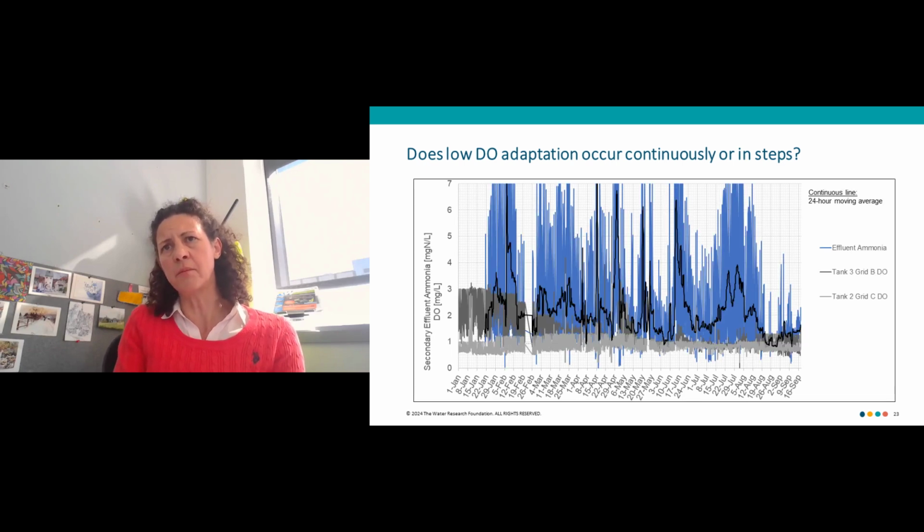And I overlaid here for the same time period the effluent ammonia concentrations, because there is a variability diurnally. You see that this data looks kind of smeared, but that's just the diurnal variability of ammonia in the effluent. And specifically, I don't have a pointer, but look at August of this year. So towards the end, we suddenly saw a decrease in ammonia that we pay attention to in the third webcast specifically.